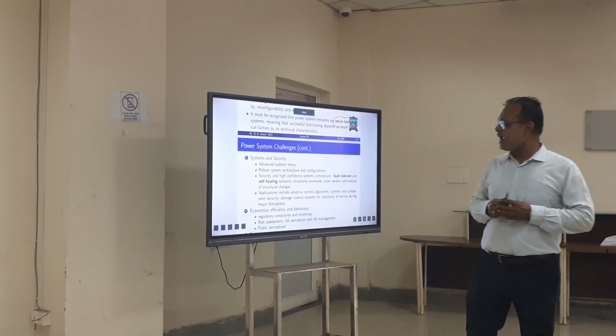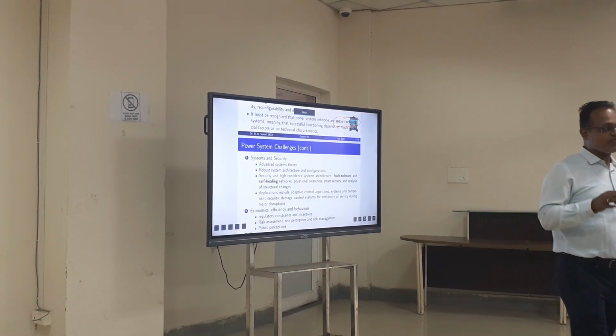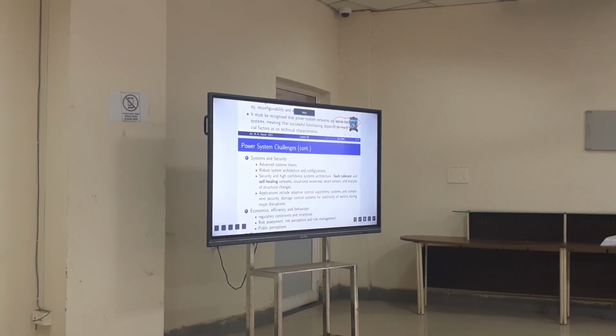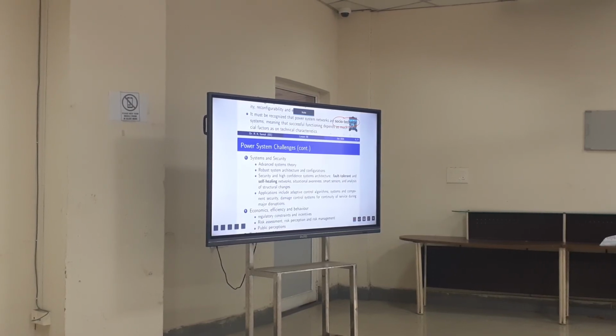Okay? And you as electrical engineers should be able to explain to everyone the difference between energy and power. If someone puts a solar PV on his rooftop, it doesn't mean that he will charge his vehicle from the PV directly. No, it doesn't happen that way. Because the vehicle may need 5 kilowatts of power, whereas the solar may only generate 2 kilowatts at a time. But energy-wise it can be.